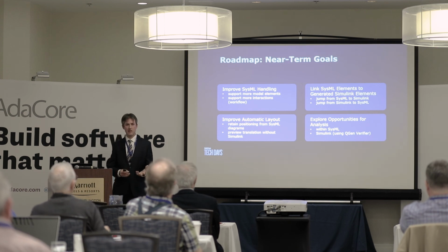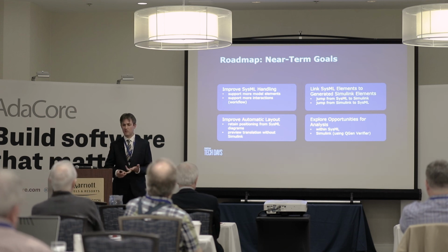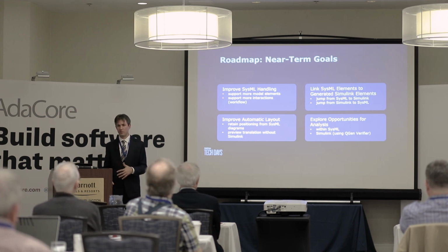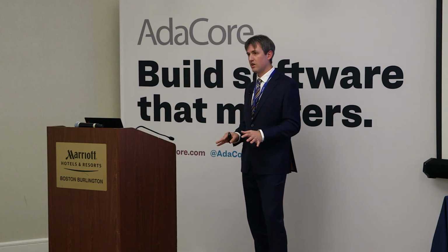So we'd like to conduct analysis within SysML so we can look at these formalized requirements and ask if they're consistent, ask if they're complete, ask if they have entailment of other higher level properties. And we'd like to be able to prove that synchronous observers that are generated in Simulink are always satisfied, for example, using QGen verifier.